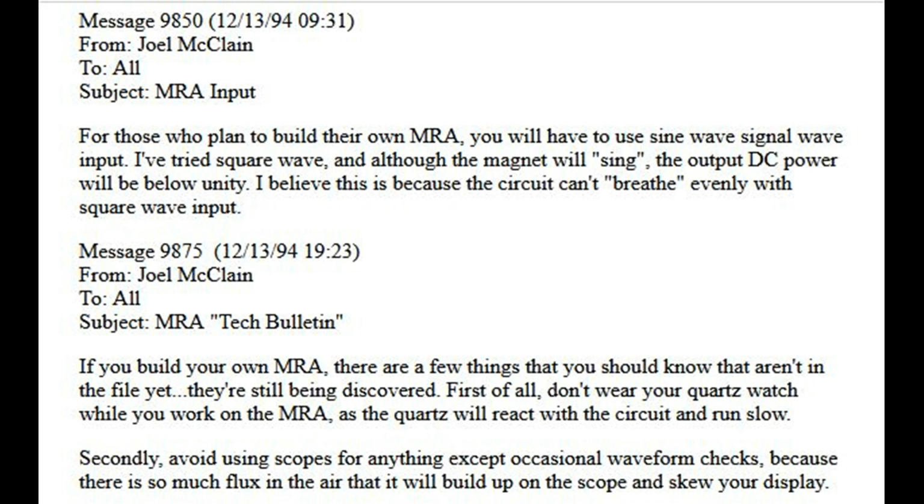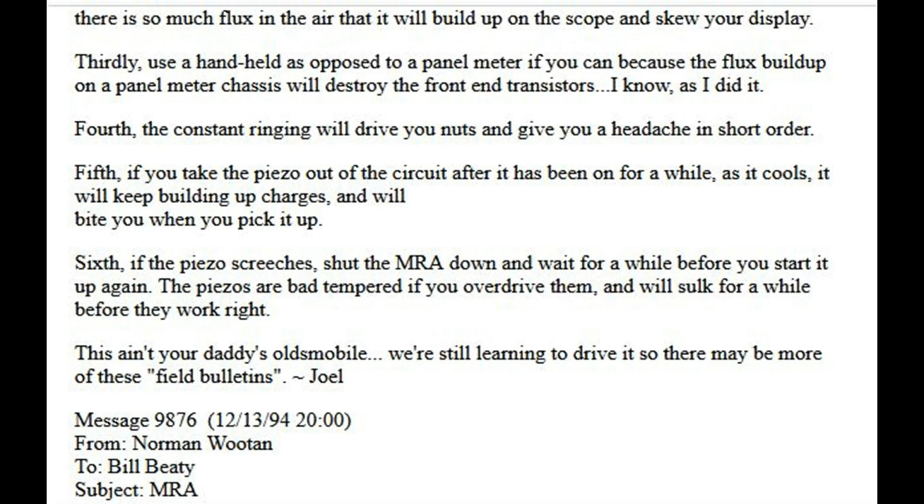Secondly, avoid using scopes for anything except occasional waveform checks, because there is so much flux in the air that it will build up on the scope and skew your display. Thirdly, use a handheld as opposed to a panel meter if you can, because the flux buildup on a panel meter chassis will destroy the front end transistors. I know, as I did it.